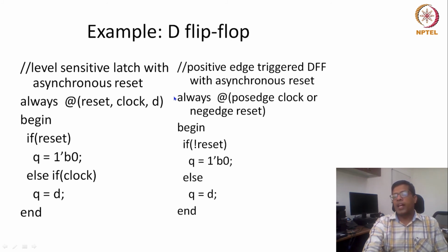Because we are writing this always block with positive clock edge and negative reset, the synthesis tool will be able to identify this kind of syntax and act accordingly whenever it is there. So sort of pattern matching would happen, and this would be synthesized as a flip-flop in case of hardware synthesis also.